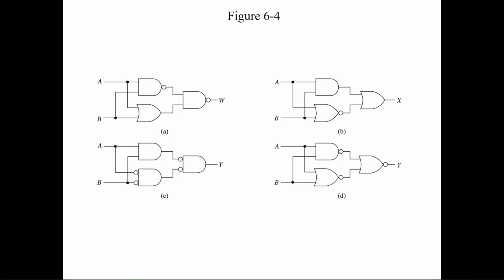So when they're inverted, they're NAND. When they're inverted on the output side, yes. Okay. So then this one has inverted AND gates because the signal's coming through inverted on the front end, not the back end. Anybody see that?